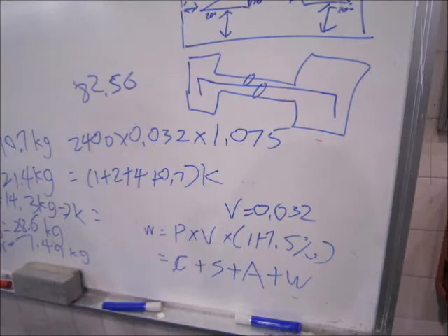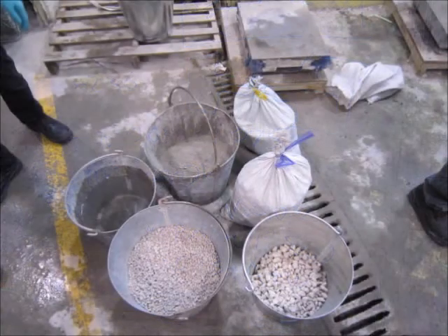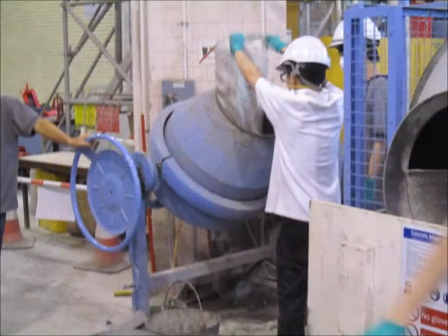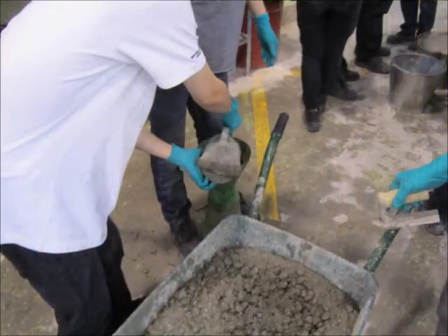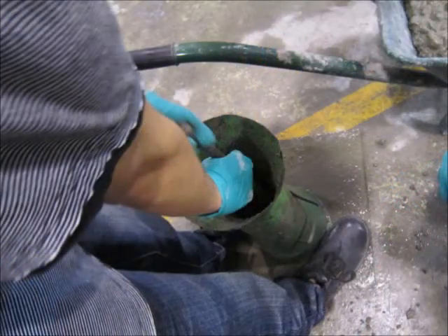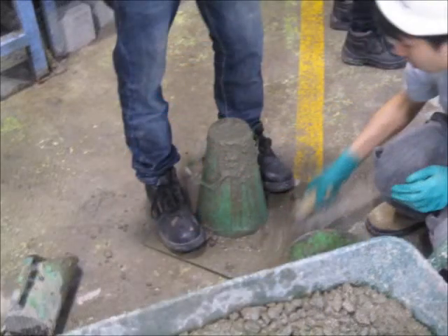In the concrete training, we used to provide a formula to calculate the weight of all the materials, such as cement, sand, coarse aggregate, fine aggregate, and water. When mixing the materials, it is essential to mix the coarse aggregate and fine aggregate first, because the cement and sand cannot mix with other materials entirely when they are at the bottom. After that, we put the cement and sand into the mixer. Finally, we add water to the mixer and start the mixer to make concrete.